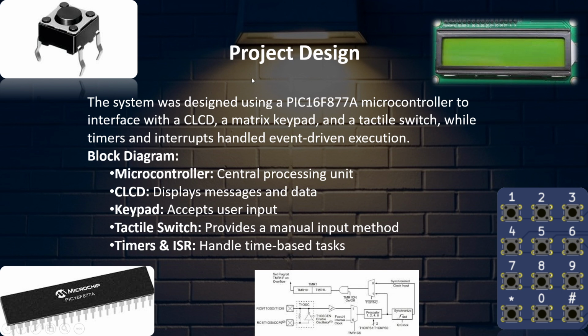Here let's see our project design. The system was designed using a microcontroller. As I was saying before, our microcontroller was called PIC16F877A, and that microcontroller was used to interface with a CLCD, a matrix keypad, and a tactile switch, while timers and interrupts handled event-driven execution.